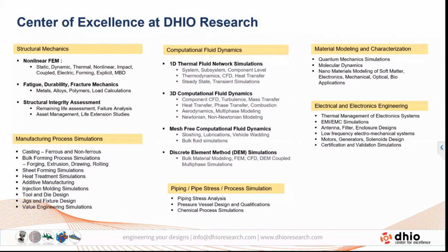So the major activity here is on structural mechanics. We work on the complete range of nonlinear FEM, whether it is static to dynamic, linear to nonlinear, thermal, explicit, implicit. So that's our starting point for all the activity. And then we work on fatigue, durability, and fracture mechanics, and that's our core strength. Not just metal fatigue, we also work on polymer fatigue, like assessing the life of elastomers and polymers, whether it can be a tire, rubber bush, or any of the elastomeric materials.